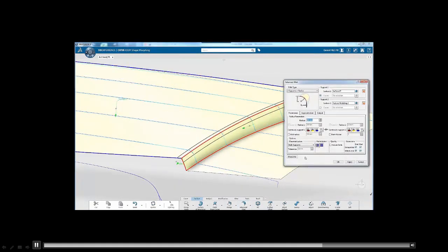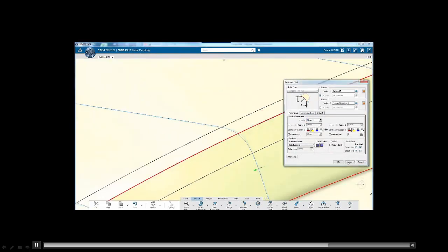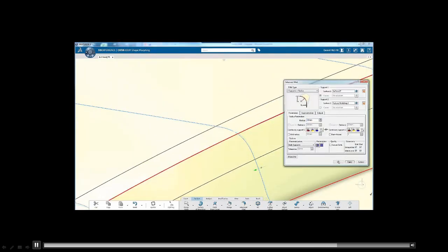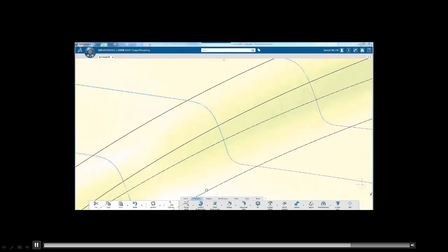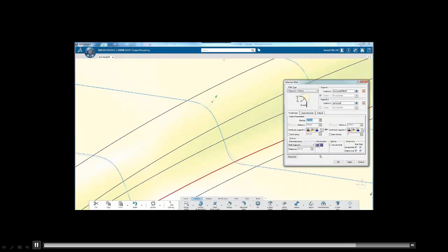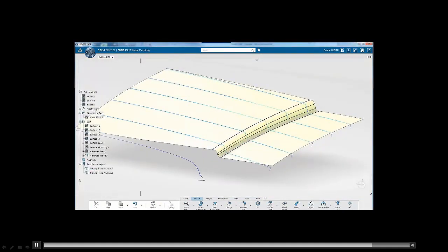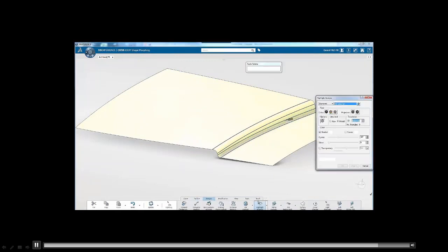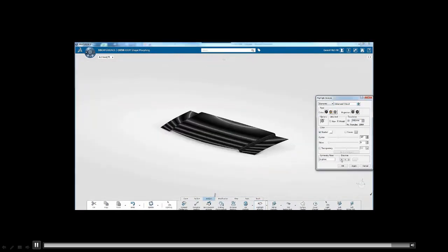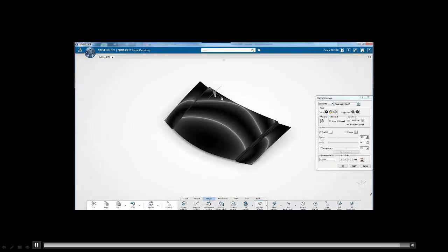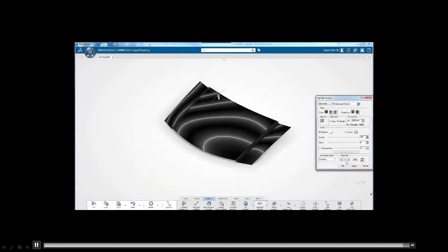reacts. And now finally we're at the filleting stage. A lot of very powerful fillet tools in CATIA ISOM, which we don't have time to cover today, but there are plenty of ISOM webinars where you can get more information on this. And finally, we're just putting some highlight analysis, zebra stripes, on the hood, ensuring that we don't have any issues across the center line.